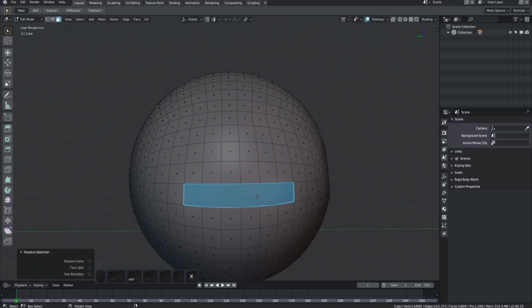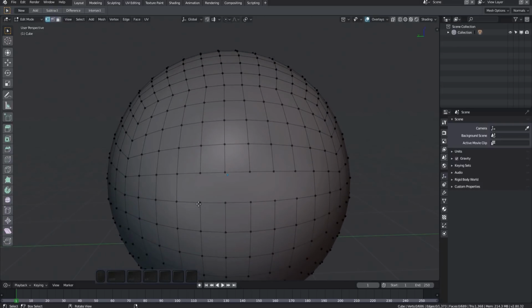In a case like this, you may not want to merge, but connect the individual vert pairs, like the bridge tool would do, if there weren't a polygon. You can do that with Smart Vert, by using the Ctrl-Alt-1 shortcut, or by changing the mode from Merge to Connect in the Redo panel.